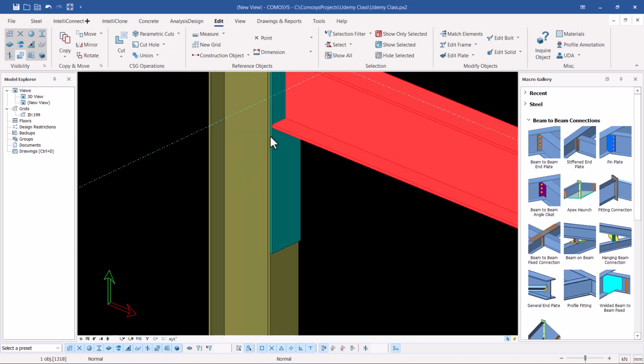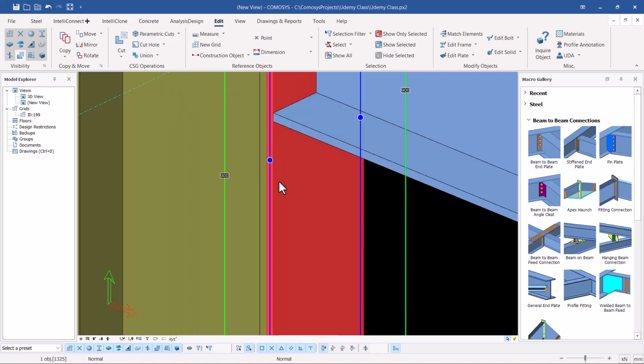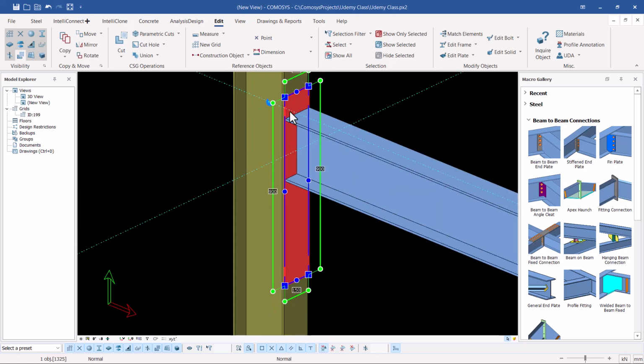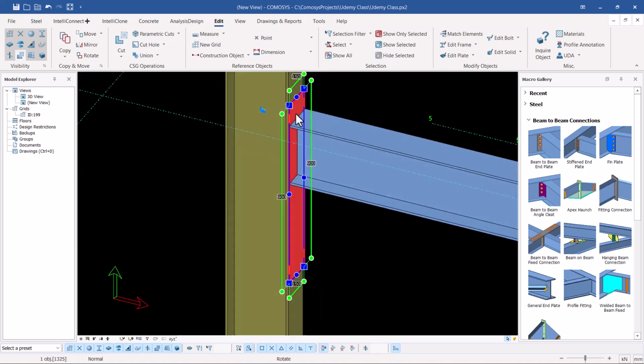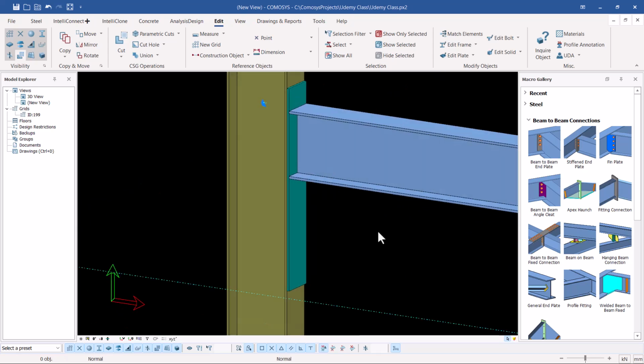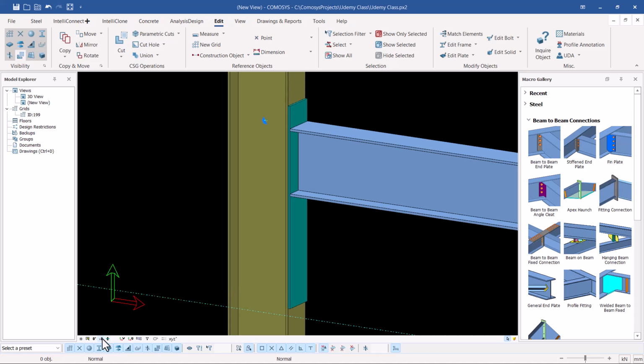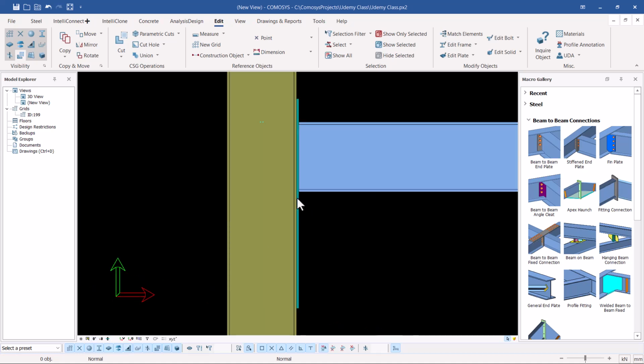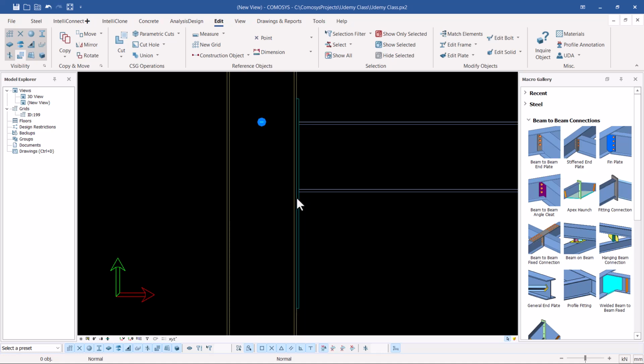We've created a plate there using a sectional tool right there. So I'll right click and hold my mouse and turn that around like that. You can always come to sectional view once again and create a haunch. So how do you go back to sectional view? Just click on that 0 and maybe change the view. Press Ctrl D till you get the draw mode of your choice. So we can always go back and create a plate somewhere here.